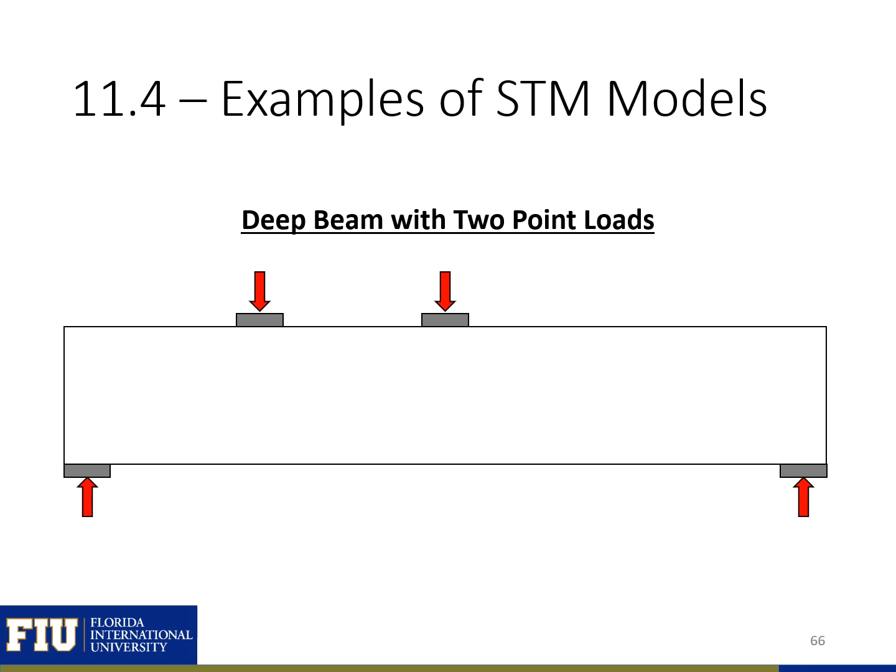The next model we'll develop is for a deep beam with 2-point loads. So again, if you want to try to develop your own model, then pause the video here. The first thing that we can do is lay out the location of our nodes. So we can put some nodes above our supports, under our loads, and then we'll put some here in this longer span.